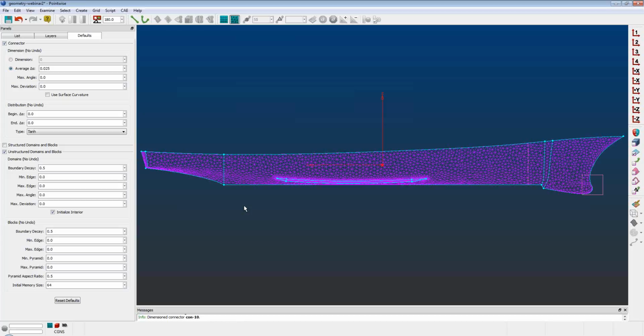All right, let's go to Arash Eslamboost. Yeah, hi there. My question is about growing prism layers on top of a surface mesh. Sometimes in sharp corners, when I grow these prism layers, after multiple layers, let's say 5 or 6 depending on the geometry, the surface doesn't appear smooth anymore, becomes jagged, and eventually crashes. Is there any opportunity to fix this?